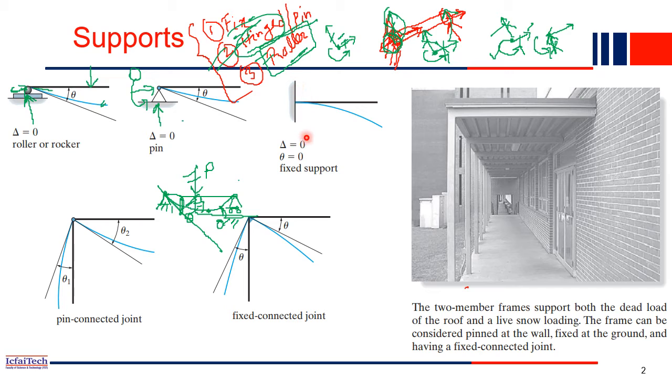So now this is the third category, that is, if your joint is a fixed joint, right? That is what I have written here as fixed, shown here. The fixed category means this point won't move in any direction, right? This point cannot move horizontally, cannot move vertically, and cannot rotate also. Means you have a fixed end moment.